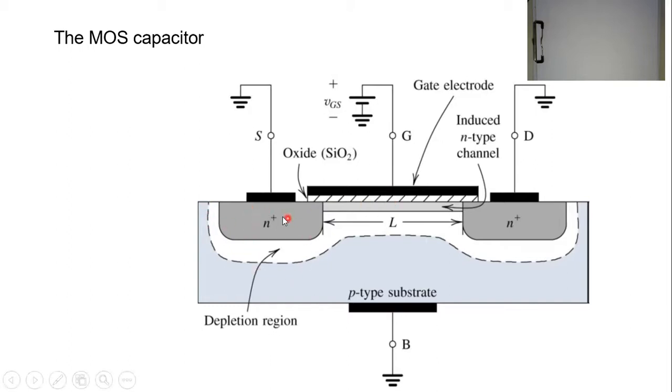If you look here, my dear students, this is the source, which is an N type, and this is the body or the substrate, which is a P type. Accordingly, herein we have what's called a p-n junction. So a p-n junction means that you have a capacitor based on what we have learned in chapter number 2. Similarly, on the right-hand side, you have an N-type drain region and a substrate, which is a p-type. Accordingly, you have a p-n junction. Then you have another capacitor.